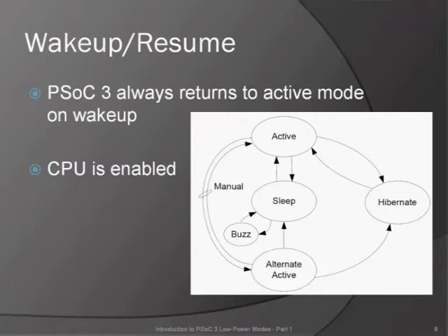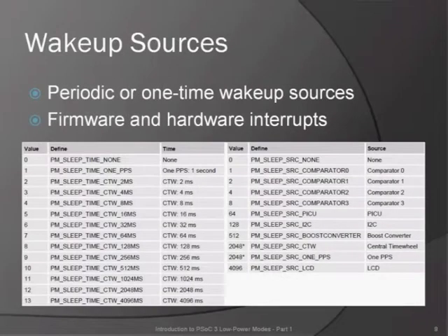When a wake-up event occurs, the PSoC 3 is always returned to active mode, and the CPU is automatically enabled, regardless of its previous configuration settings. Active mode is always the default power mode at startup. Wake-up events are configurable and can come from an interrupt or a device reset. A wake-up event always restores the system to active mode.